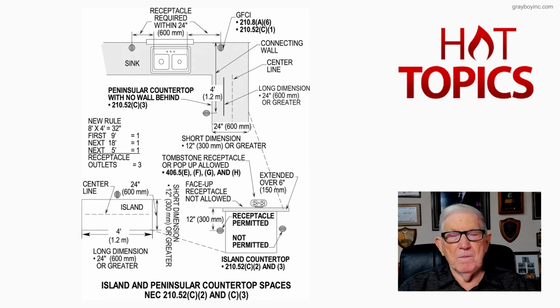of the island. So that's what this figure is illustrating: the island and peninsula countertop spaces are required to have receptacles now based upon the dimensions of the island. So that's what this NEC 210.52(C)(2) and (C)(3) is illustrating to the user of the NEC.